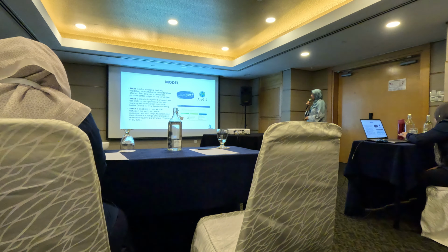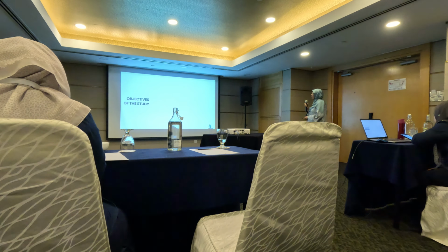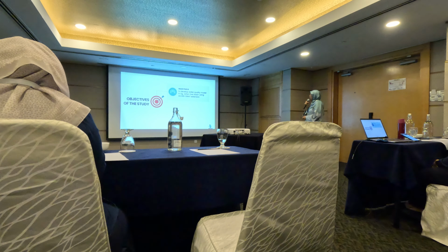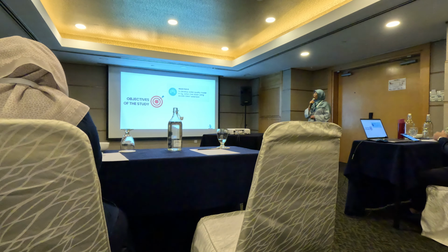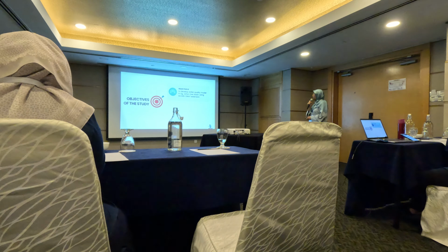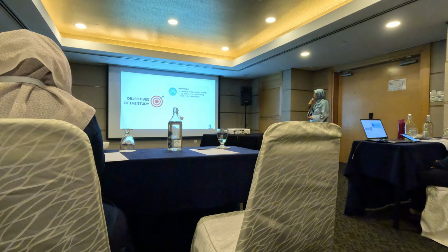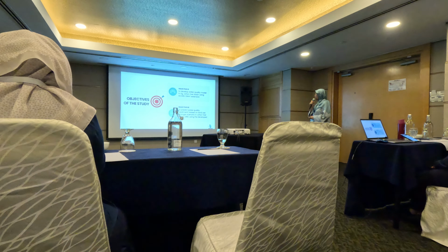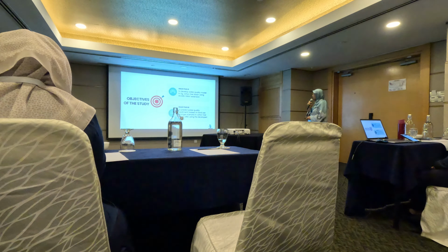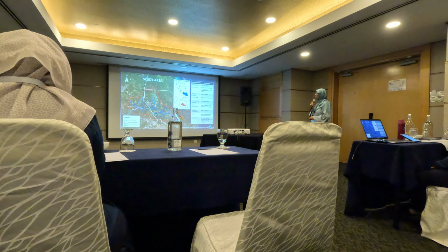There are 2 objectives in this study. Firstly, to develop water quality modeling in Sungai Johor River Basin using the SWAT extension. But for today, I only highlight the sediment parameter. For objective 2, to predict water quality, which is sediment, based on land use change scenarios in Johor River Basin using the developed model.